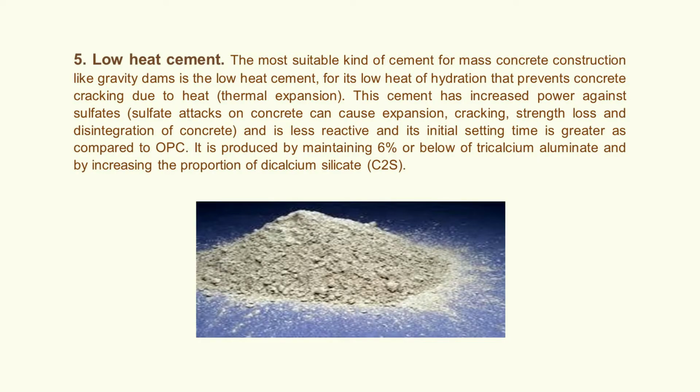Next is low heat cement. The most suitable kind of cement for mass concrete construction, like gravity dams, is the low heat cement for its low heat of hydration that prevents concrete cracking due to heat or thermal expansion. This cement has increased power against sulfates.